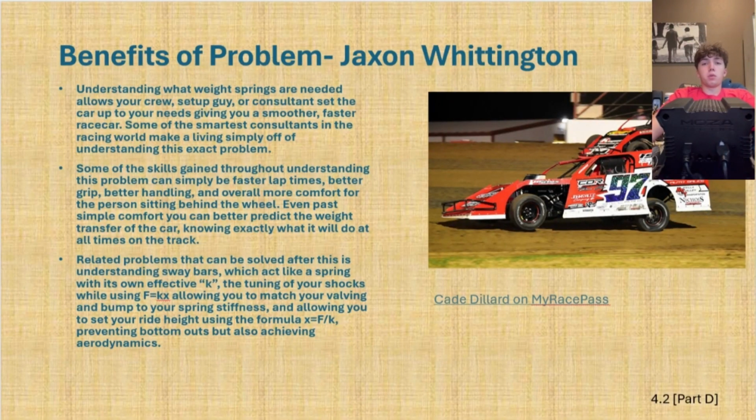So what is the overall benefit from understanding this problem? Well, if you understand F equals Kx, or just the entire spring problem in general, you can better understand how much softer or stiffer of a spring you need, how much longer or how much shorter of a spring you need, to adjust the car to what the driver likes.